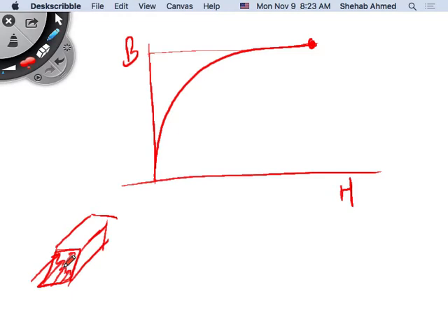You're not generating any more flux, right? You're increasing current this way to push more flux lines. This is proportional to the magnetomotive force, which is proportional to Ni, right? So if you keep pushing more current, you're not getting more flux lines pushed into the core because the core has saturated already, right?